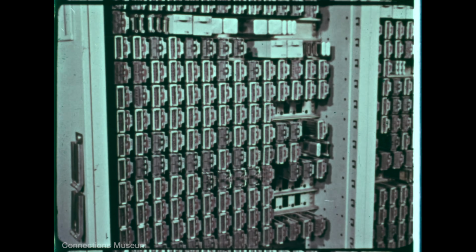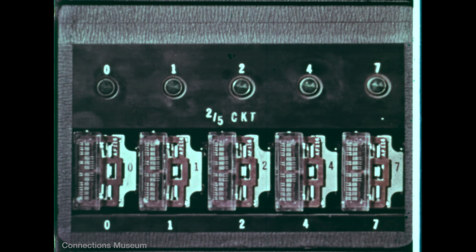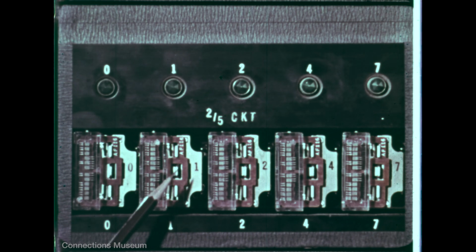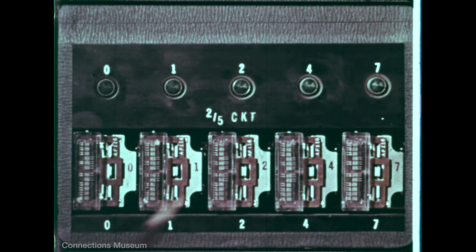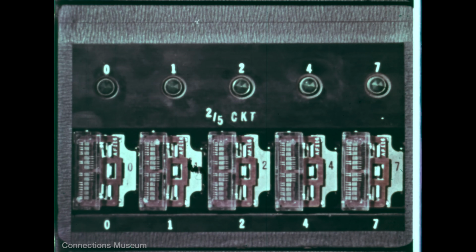Telephone systems also use electromechanical memory devices. Banks of relays store temporarily routing directions for a telephone call. Simpler and faster than the punch card, access to a stored bit takes less than 1/100th of a second. 5 relays using a variation of binary representation called 2 out of 5 are used to store each digit of a telephone number. The relays are designated 0, 1, 2, 4, and 7. 2 relays are operated at one time for each decimal digit.